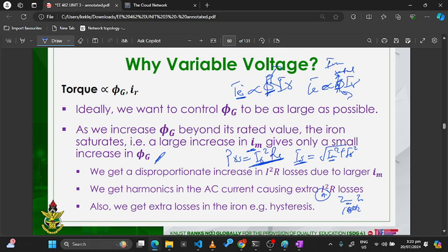The third harmonic will have like 150 hertz. Is that okay? And that component is going to have a harmonic voltage. If you have a harmonic voltage, it's going to produce a certain slip, and the slip will be higher. If the slip is higher, that means even the rotor losses, the P slip, is going to increase. Because if the slip increases, the P slip will increase, because the P slip is equal to s times Pag. Is that okay?